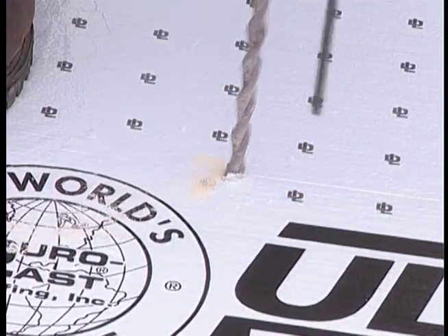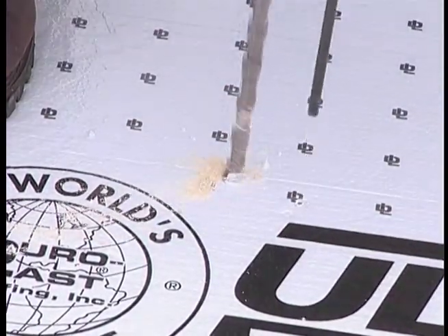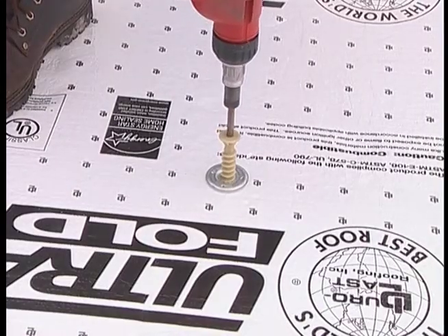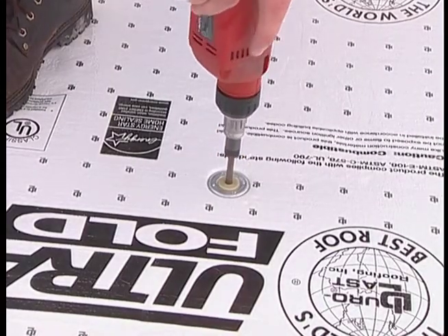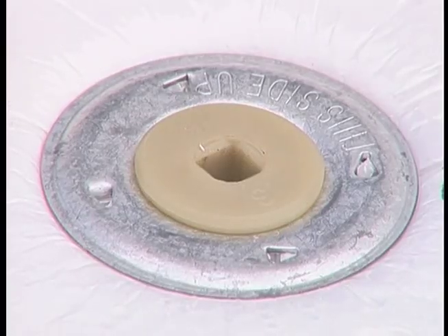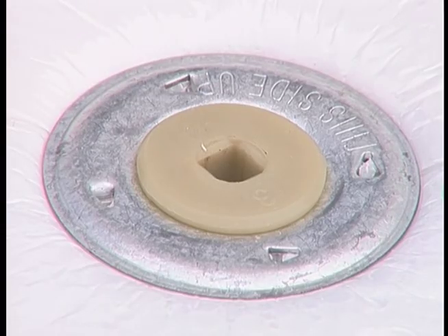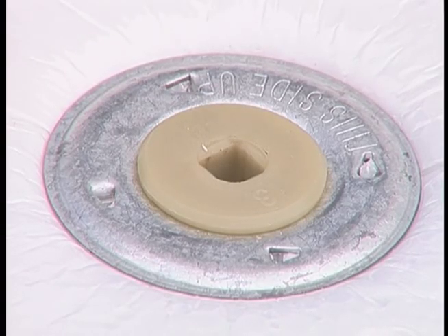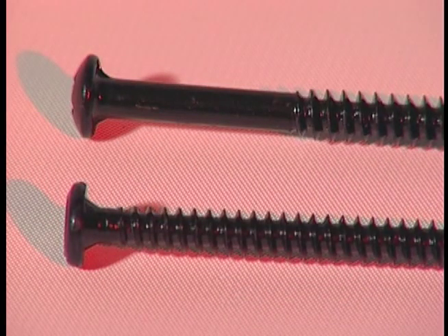For lightweight concrete and gypsum, pre-drill a 1/2 inch round hole, then install the fastener a minimum of 1.5 inches into the deck. The NTB requires a punch to set the backout wires. The auger does not. Do not pre-drill cementitious wood fiber decks. If gypsum or lightweight poured concrete are used over a metal pan, it may be beneficial to consider using number 14 or 15 screws driven into the metal.